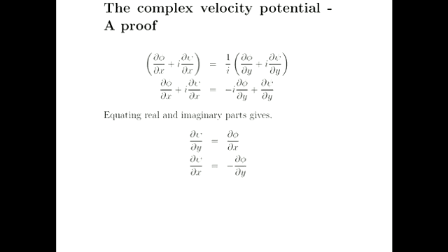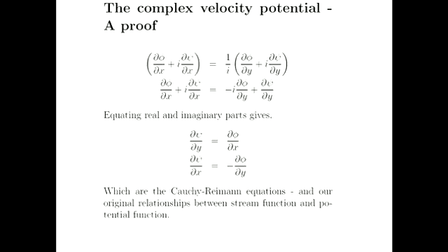So for that complex function to be true, you can see that you automatically arrive at that Cauchy-Riemann set of relationships. Okay, so the two are interrelated. If you have a potential function and a stream function that's related in this way, then I can automatically write out a complex potential function for them also.